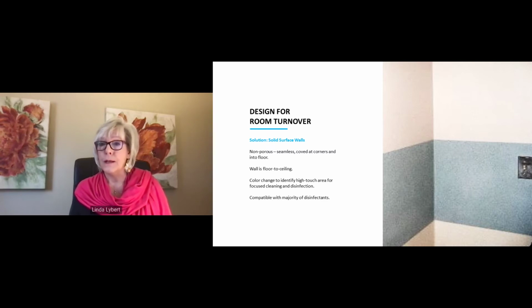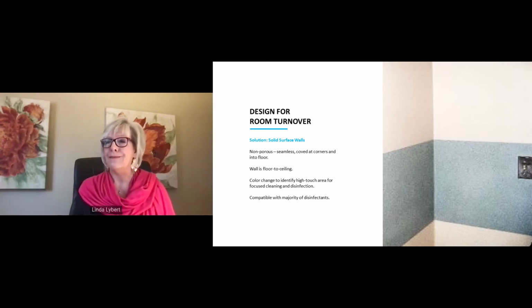What did we do? Number one, we went floor to ceiling. This is, again, an emergency department. We went floor to ceiling with a solid surface material. The material on the wall coved into the floor, so we eliminated the rubberized baseboard in the room, which was a cleaning nightmare. There was a connection point between the floor, which was not solid surface, and the coved base, but it's easier to clean that with a mop as opposed to having the top of the baseboard and the bottom of the baseboard both to clean.